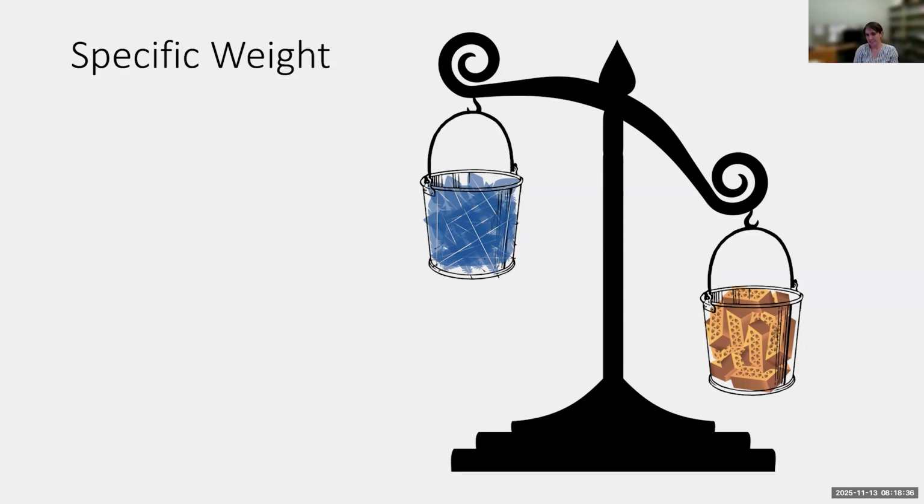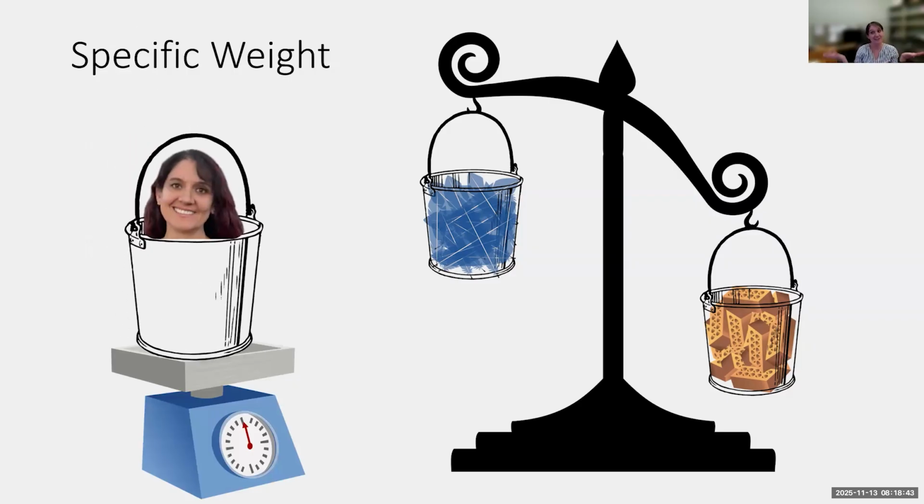So everything with a mass has a specific weight. Feathers, bricks, chlorine solution, even I have a specific weight. So we could calculate how many pounds a gallon of Michelle weighs. We just have to measure my volume and my weight. And it's important to understand specific weight because when we get to feed rate, it's going to help us convert between weight and volume.